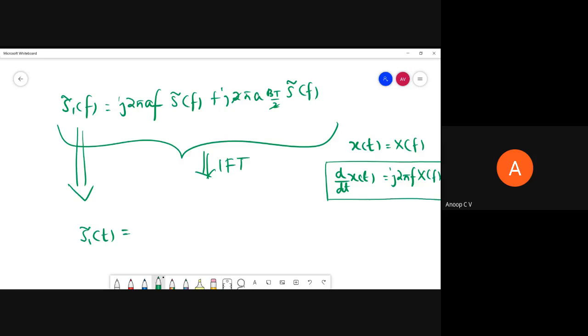So, Fourier transform of derivative, right? If x of f is the Fourier transform of x of t, then the Fourier transform of the derivative of x of t is actually what? j 2 pi f times x of f. So a straightforward evidence of this property is...